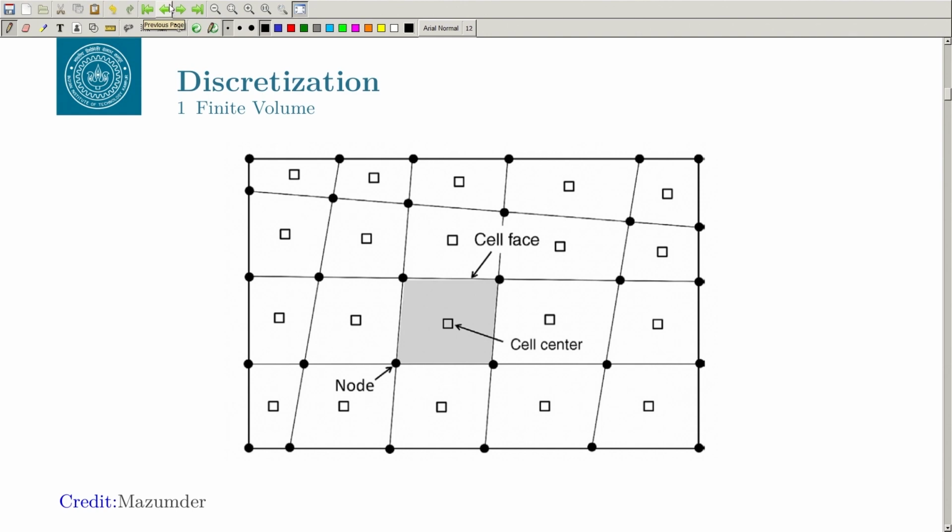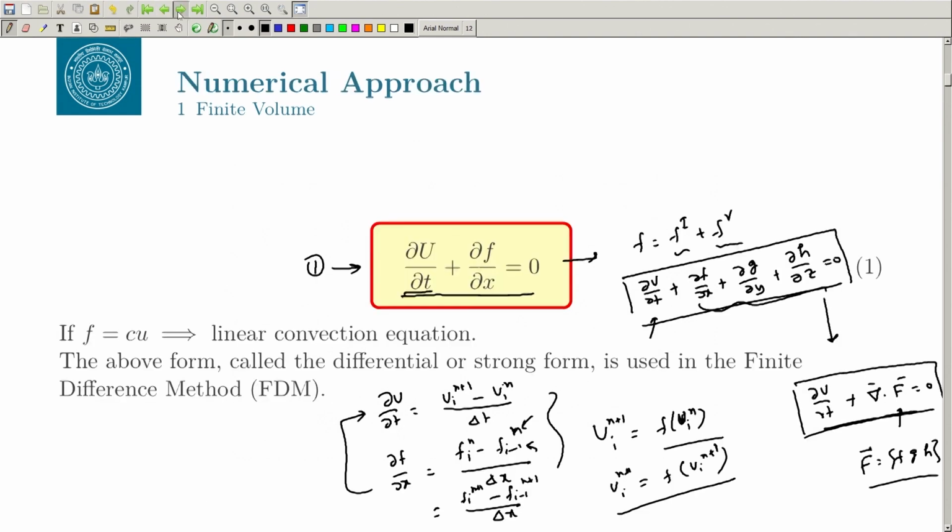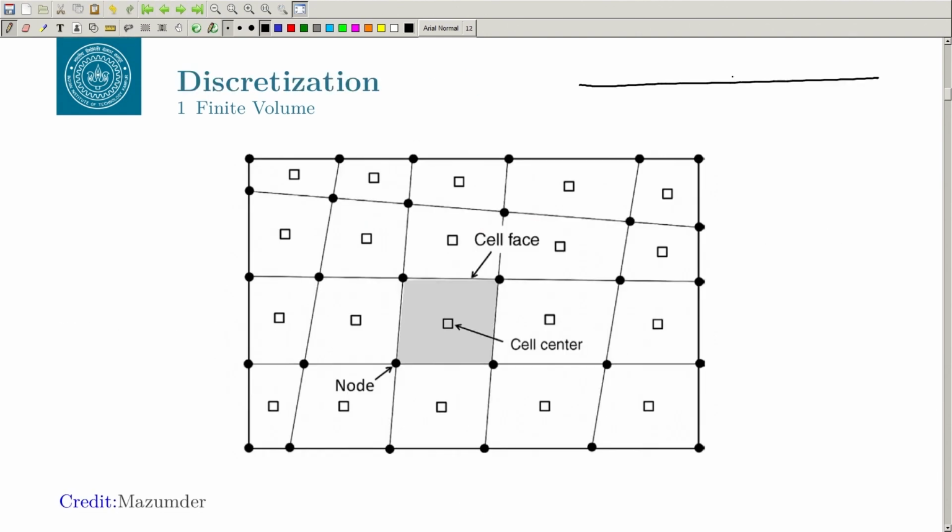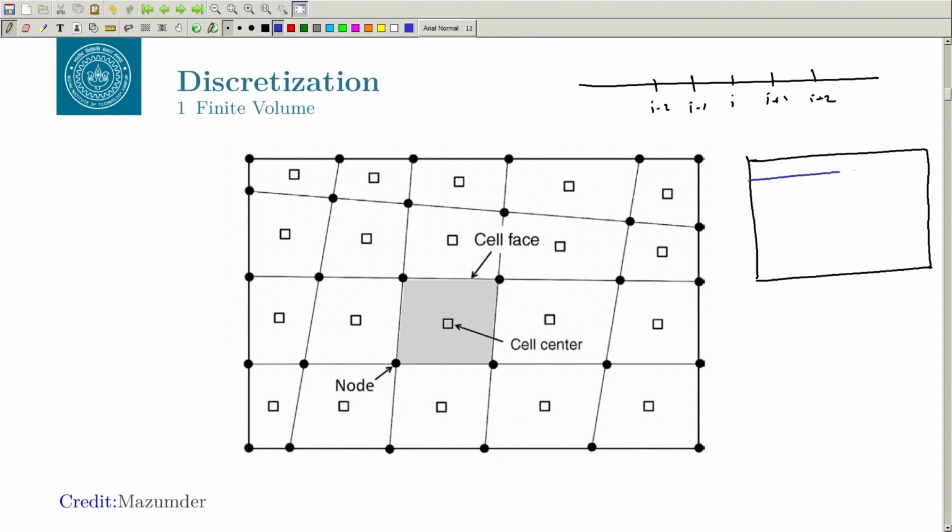So, let us say if you want to solve the problem that we had earlier. Okay. So, in 1D you are basically solving I plus 1, I minus 1, I minus 2 and I plus 2 and so on and so forth, right. If it comes to 2D, you will have a mesh like we have been discussing, for example, the case of the lid driven cavity. Okay. So, you will have a mesh which is nice and structured, right.